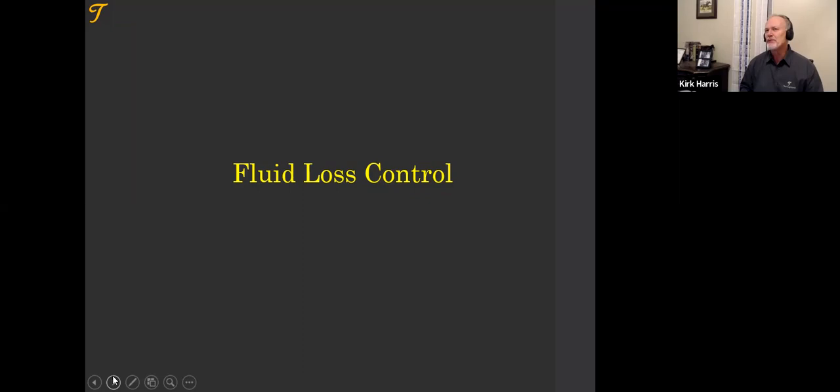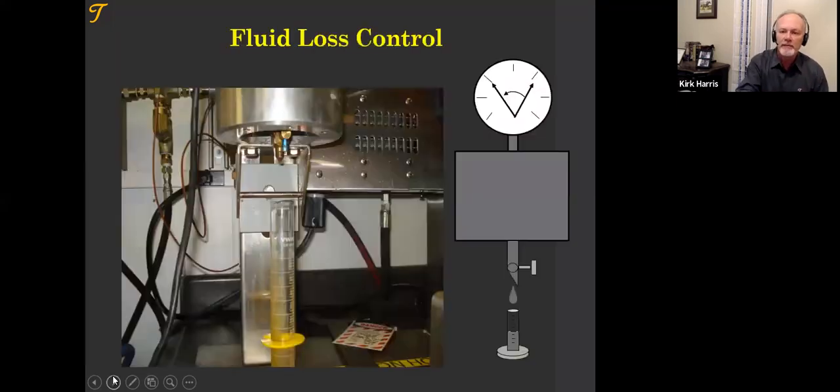Had a question the other day about putting fluid loss additive when we're in tight restrictions, pumping through bits, pumping through ports, pumping through mud motors, that sort of thing. As long as cement particles are moving, you're not going to lose fluid. We have problems with cement building up and plating out, but you don't need fluid loss additive just because you have pressure restrictions. You need fluid loss additives when those particles stop moving, and then we try to press the water out of them.